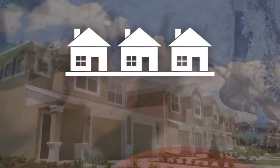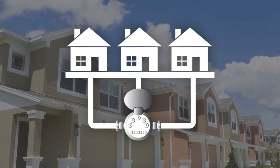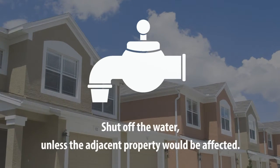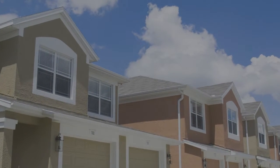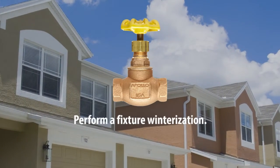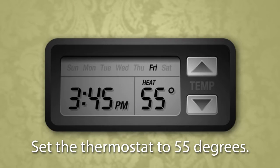If winterizing a condo unit that has a shared meter, the water meter should not be removed. Instead, shut off the water unless the adjacent property would be affected. If this is the case, perform a fixture winterization by turning off the water using fixture valves and leave the heat on, setting the thermostat to 55 degrees.